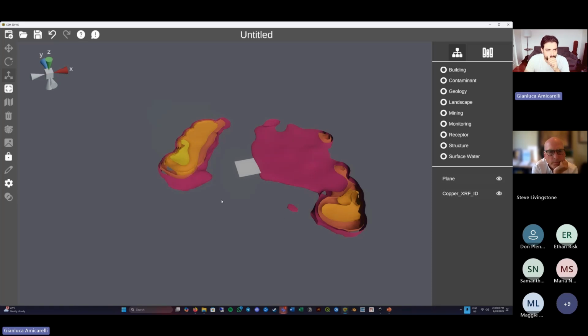What we want to do is put in synthetic points, which are basically pseudo boreholes, manually. You can go and place synthetic boreholes manually. Then those synthetic boreholes are assigned a concentration value based on the percentile distance from the closest boreholes. After that, we perform the interpolation, and this is what happens.